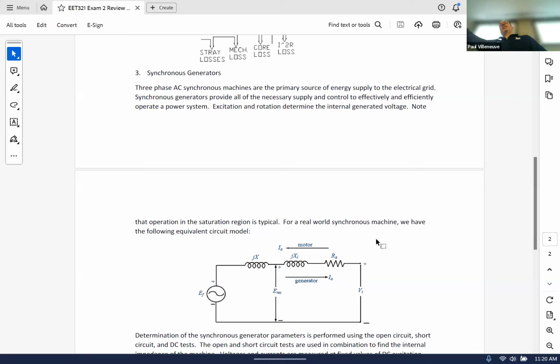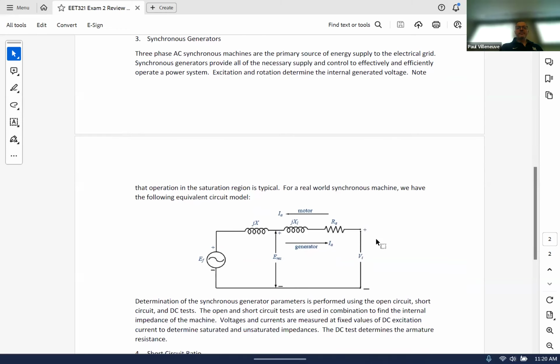So interconnecting to the grid, we talked about synchronizing a generator onto the grid. There's a little bit of a process to make sure that that's done correctly, so you don't damage pieces of equipment. So then you have two parts. You have the rotor and the stator. The stator is, because this is a generator, those are induced currents. The currents are induced based on the amount of load that's there, and they're going to cause an applied torque or induced torque that is equivalent to the current that's being drawn out of the machine.